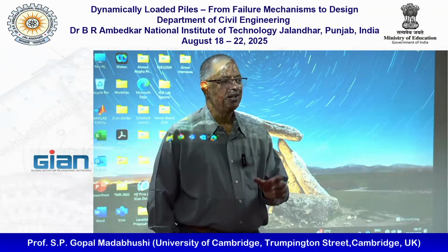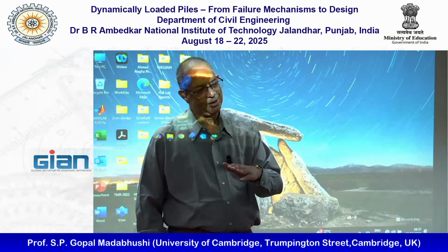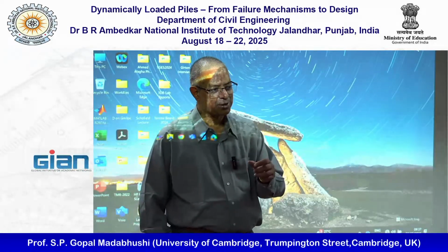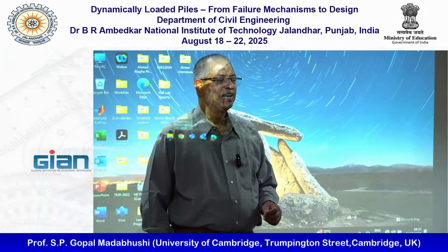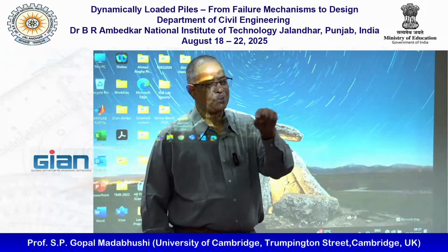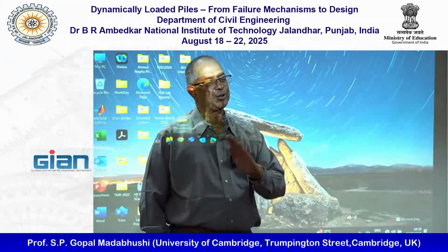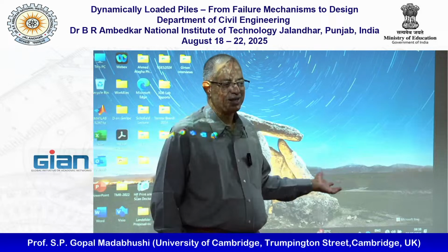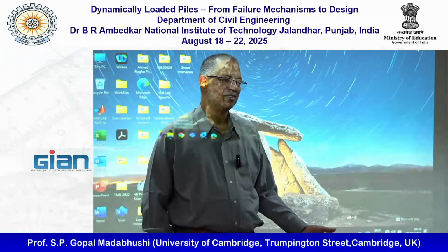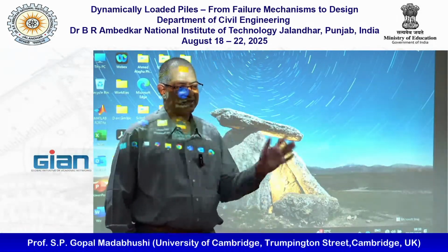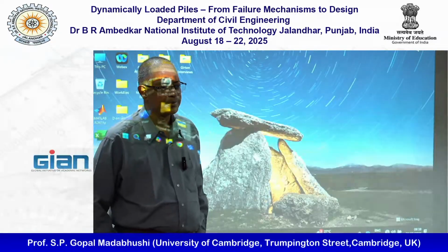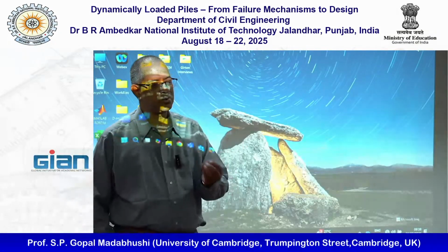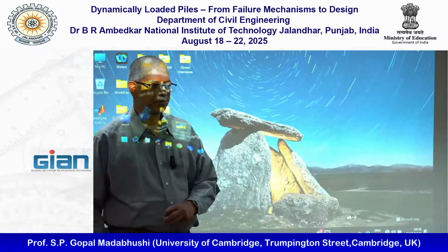More than that, the global rotation mechanism takes over. So when we reduce the spacing, because all the piles are connected through the pile cap, it's easy for it to rotate, and the bending moment has gone down in all piles. So that's why these liquefaction problems are interesting. You're starting with soil that is stiff and you're resetting. Yeah?